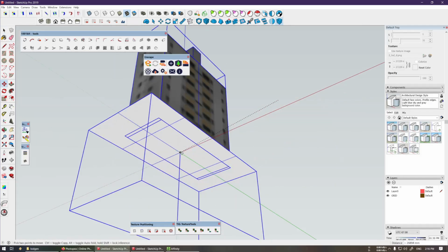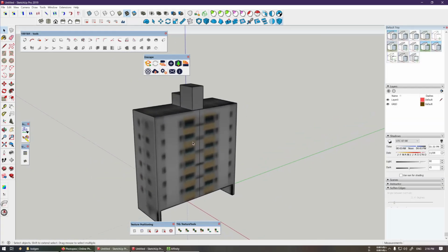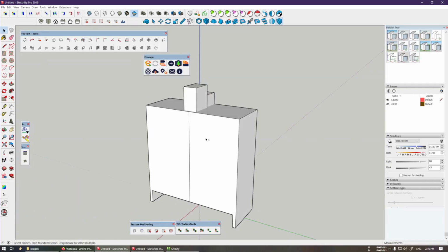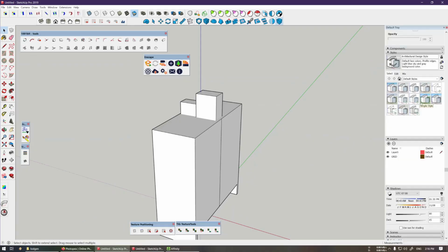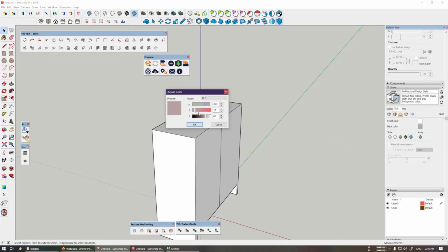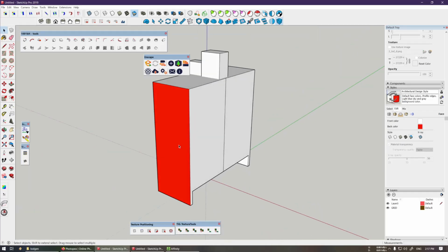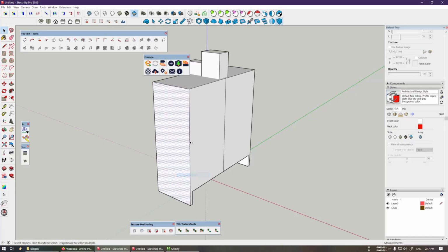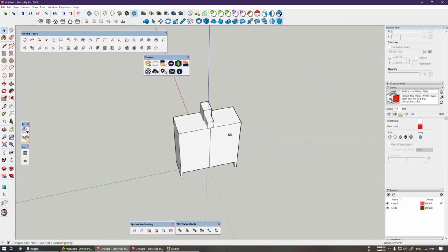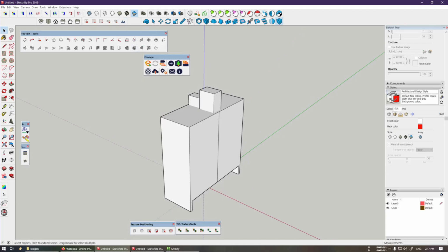So you put the center on the center of the document axis, delete the grid, explode, and then check the faces. Make sure there are no back faces oriented on the outside. You can set the back face color to red. If you have something like this, it needs to be fixed. Reverse this face. Now this is correct. Everything the player should see is white. Then you're ready to export. Make sure they are all exploded. Export asset.